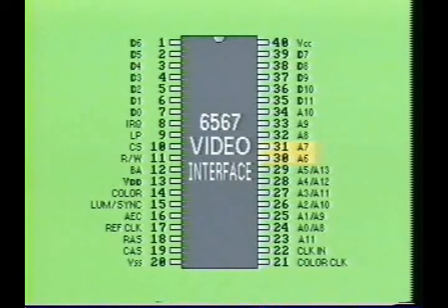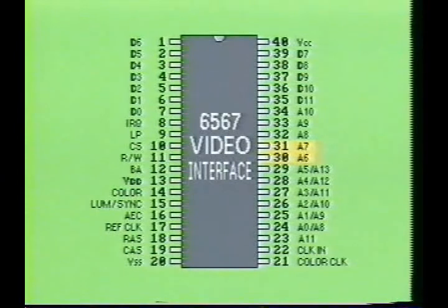Pins 30 and 31, labeled A6 and A7, are two address lines used by the chip to simply address 2 kilobytes of memory. The output of these two pins represents a form of program counter that is used by an external addressing multiplexer circuit to select character ROM and video RAM data. Notice that all of the pins 24 through 31 output addresses onto address lines for accessing its own data, much like the CPU.